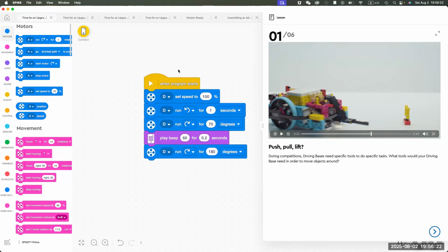I don't know if you guys remember, all right? On the main base, there are 6 holes, right? The 6 holes are the ports that you can hook up the motors. The holes can only spin forward or backward, or in other words, counterclockwise and clockwise. In order to raise this arm, you have to use the turn, right? But you translate that turn through this gear into momentum going up and momentum going down. So it's a 2-step process, not a 1-step.